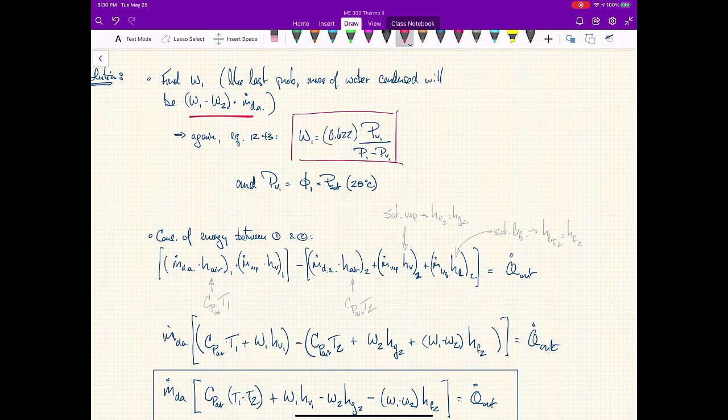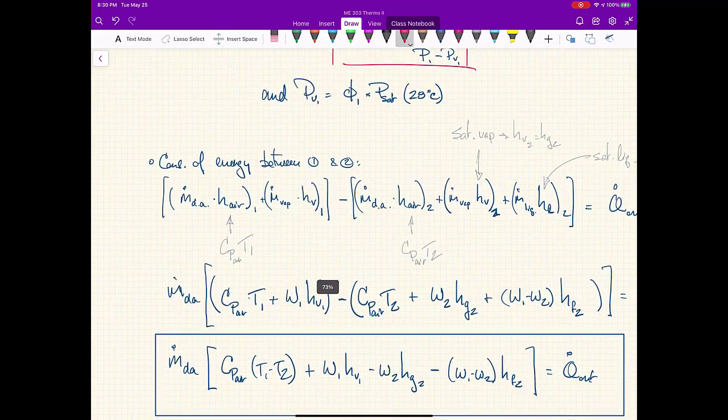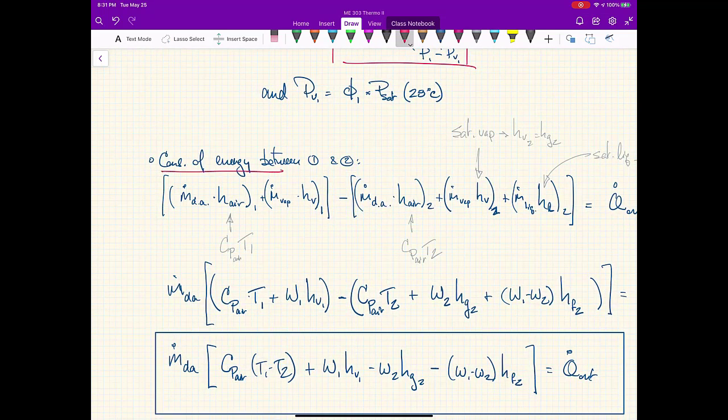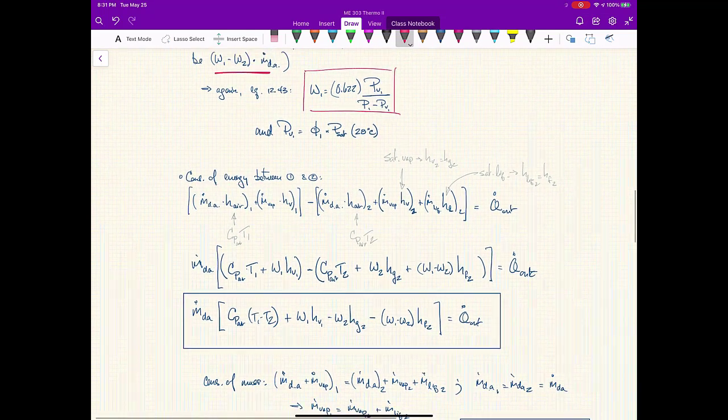In terms of model, what I do have is our old faithful conservation of energy, the first law of thermodynamics, and conservation of mass. And I'm going to make judicious use of that here to get myself to T2. When you're looking at temperature, immediately in your mind's eye, you should see, okay, I'm going to need conservation of energy in there. And so I'm starting straight off with that. Let's look at the conservation of energy between state 1 and state 2, given the assumptions that I made, no work done, etc.